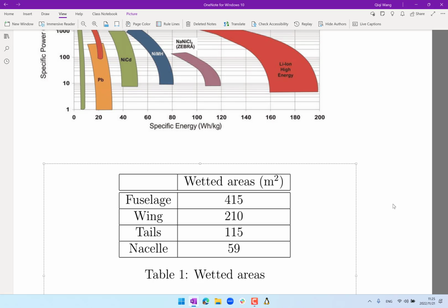They are flying pretty close to each other, and one of the things I would strongly suggest considering is how much lateral distance these 2 towing airplanes should fly apart so that you get the optimal efficiency gain by using the wake of one airplane to reduce the induced drag of the airplane being towed. Does that make sense?